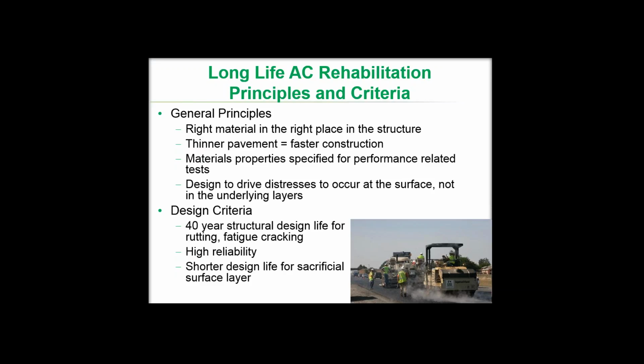And overall, what we're trying to do is to design the pavement to drive the distresses to the surface so that we can handle them through fast and relatively low-cost maintenance and preservation treatments and have the underlying layers last for decades and decades below that surface. So we're typically looking at a 40-year structural design life, high reliability, and then maybe 15 to 20 years for replacement of a sacrificial surface layer.